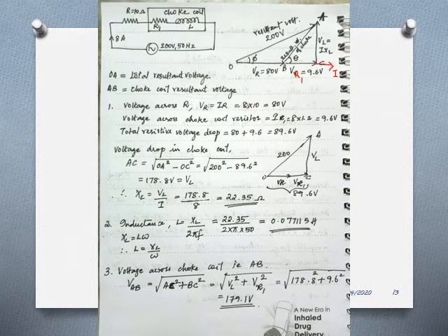First, let's move to the circuit diagram. As the question says, it has a non-inductive resistance of 10 ohm. So there is a resistance R that is equal to 10 ohm and a choke coil. I have mentioned it earlier, a choke coil meaning it is a combination of resistance and inductance in series. If you consider or take the choke as an inductance alone, you will end up in a wrong answer. So always remember a choke coil meaning there is a resistance and an inductance in series.